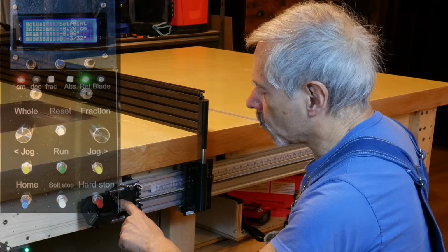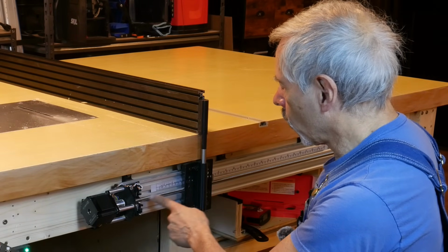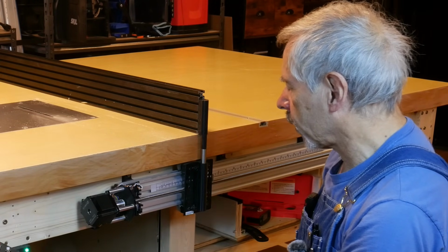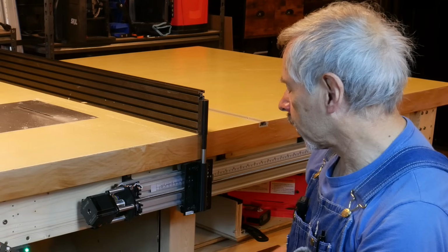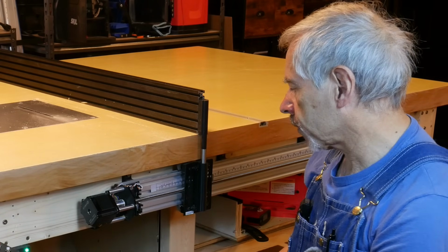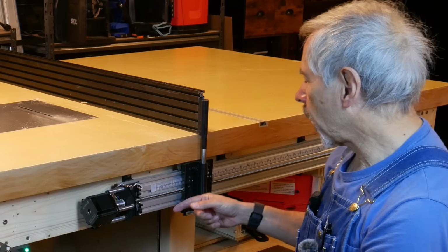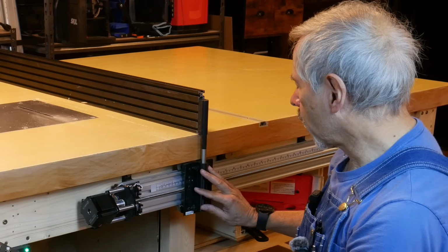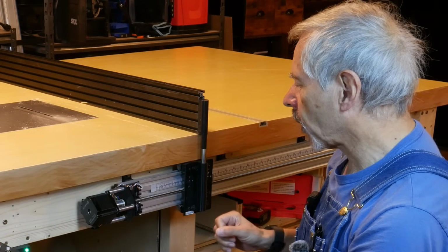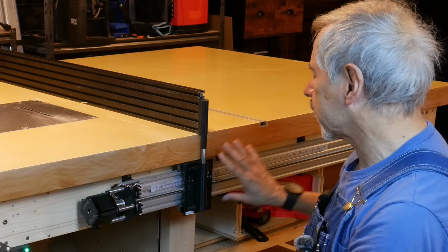So you see the motor is rotating, and the motor is connected to a lead screw. This particular lead screw is very popular and has become quite inexpensive because it is widely used in 3D printers. This lead screw is designed in such a way that for every full revolution that it makes, it advances this carriage by 2 millimeters.